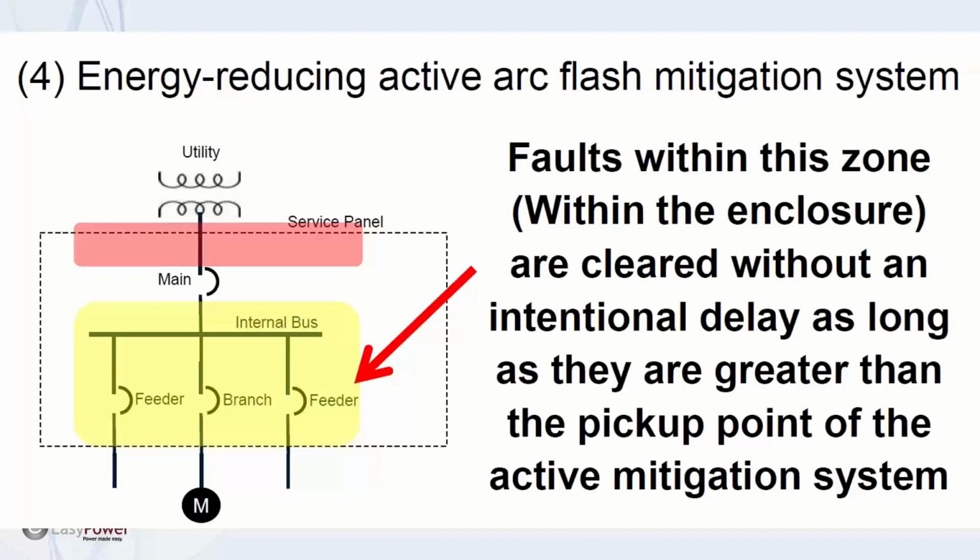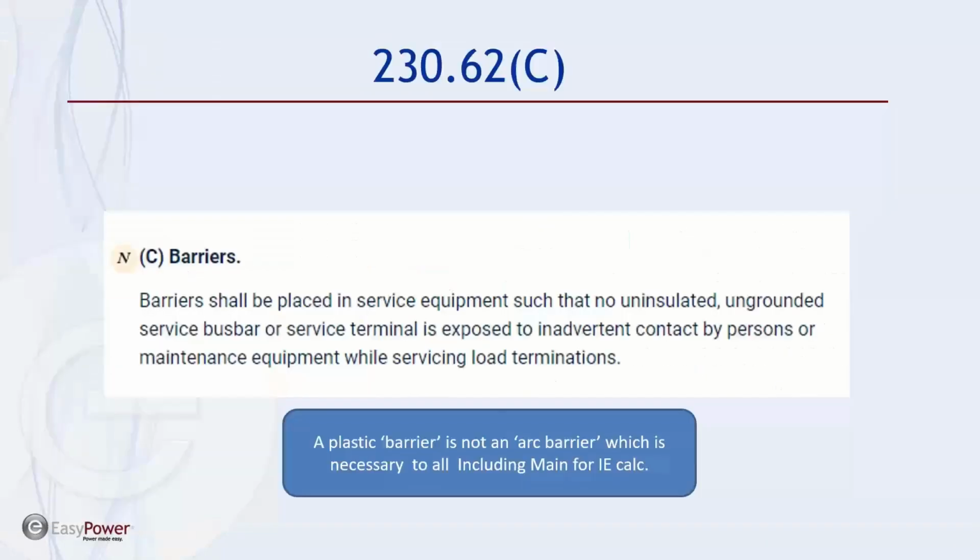So again, this can be in a relatively short amount of time, in terms of 10, 15 milliseconds, and be able to get a very quick reaction time. And again, this is set up in EasyPower similar to the differential, because we can't simulate the light sensitivity, and so that's how it's implemented in EasyPower.